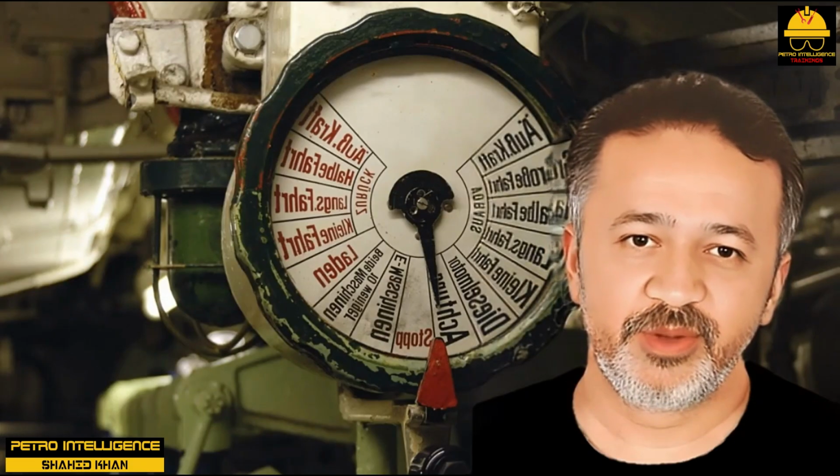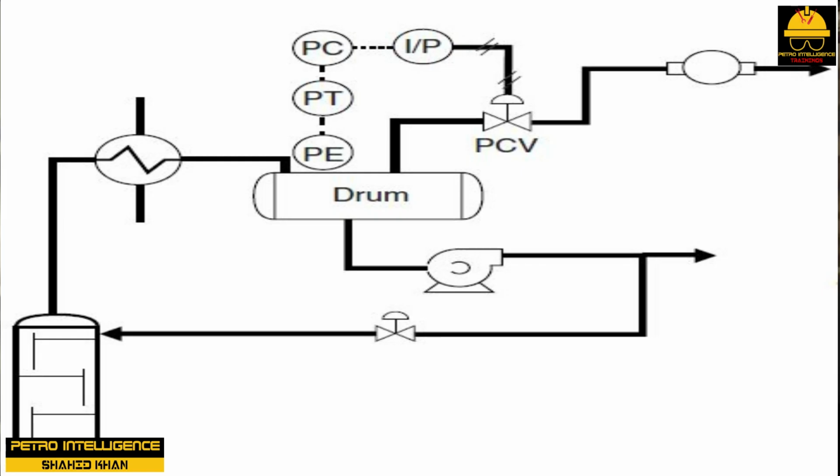Pressure control loop. Pressure control loop design has the same elements as temperature, level, and flow control loops. The one area that changes consistently is the first, primary elements and sensors. Pressure control loops use devices to detect and respond to pressure changes. These primary elements are typically expansion-type devices. This picture includes a pressure transmitter, controller, transducer, and control valve.